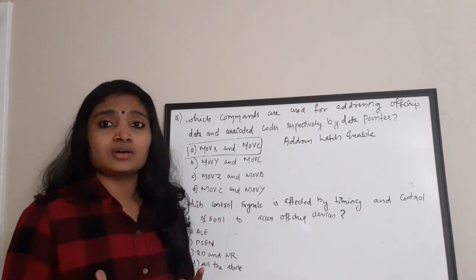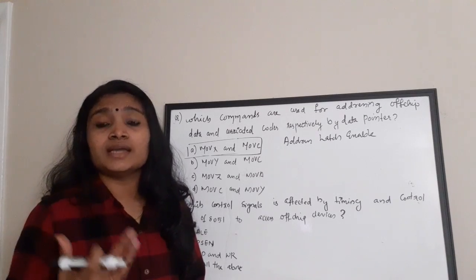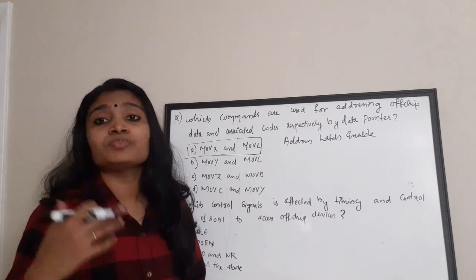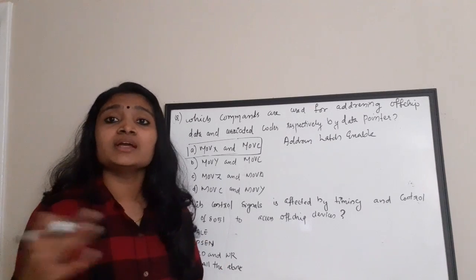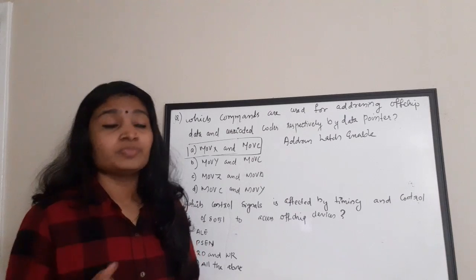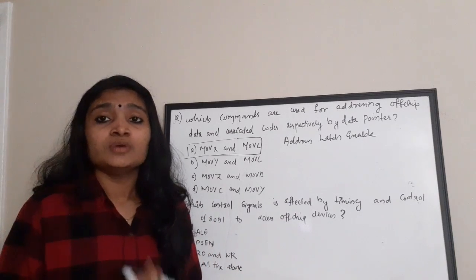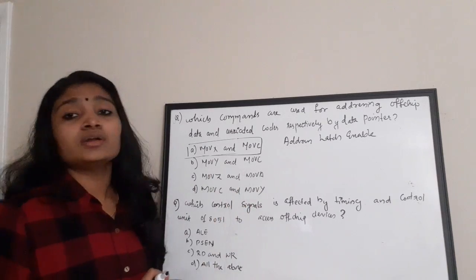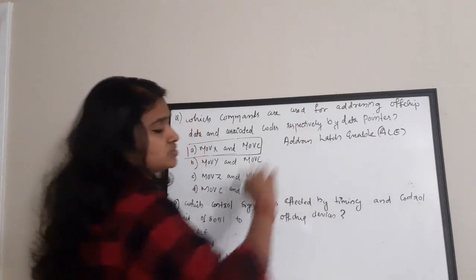So we have talked already in the beginning of this video that we can connect 64 kilobytes of external memory to the 8051 microcontroller. And if we want to access that external memory, we can use this ALE, or address latch enable. So how to use this?